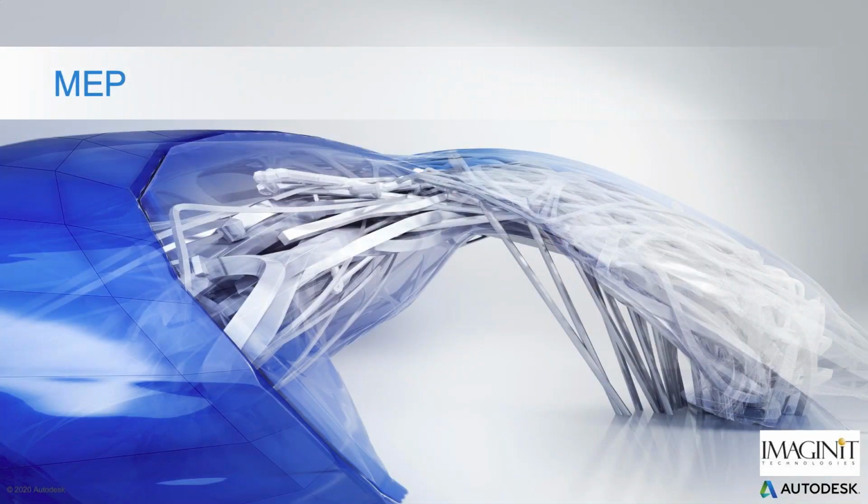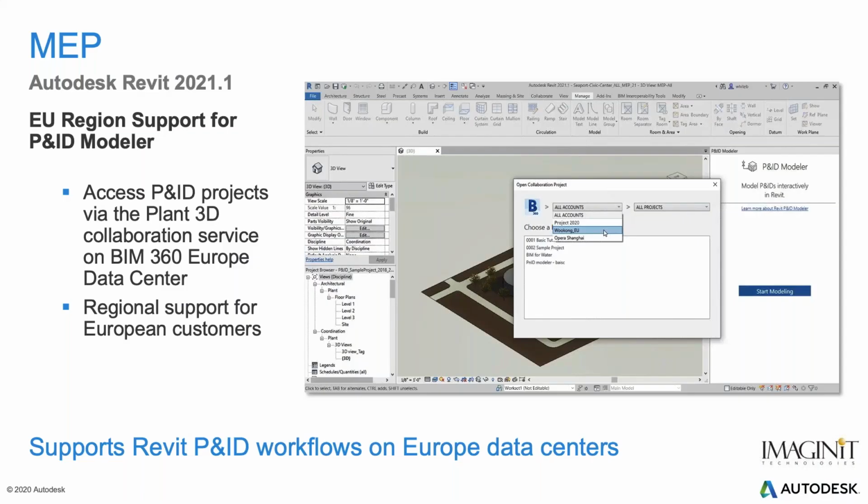Okay, so some MEP improvements. I get a lot of questions about the P&ID modeler, so this is kind of nice. After selecting a Plant 3D project on a Europe data center, in Revit 2021.1, you can now access the P&ID projects hosted via the Plant 3D collaboration service on BIM 360 Europe data center locations. Bottom line here is the new feature makes it possible to connect the P&ID modeler and Revit projects on the Europe data center locations. I don't know when this is going to come stateside, but it's still a good step in the right direction.